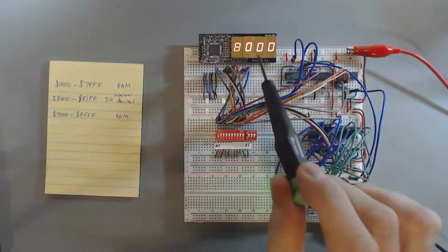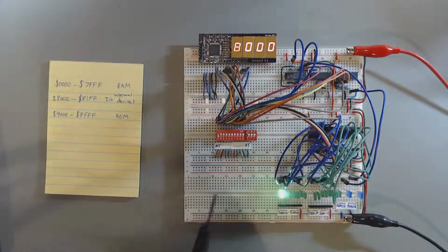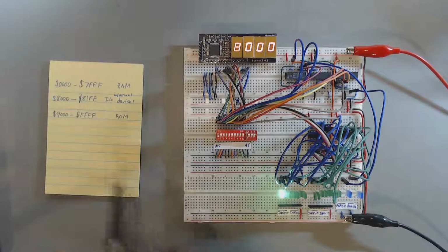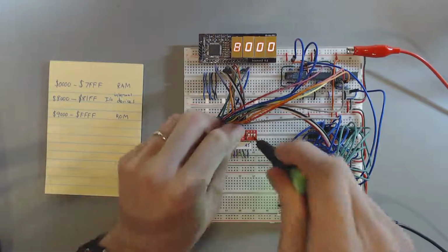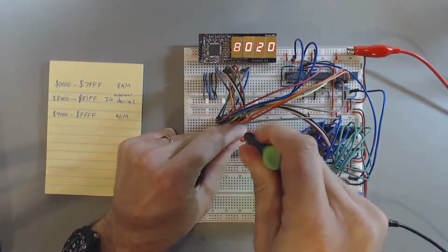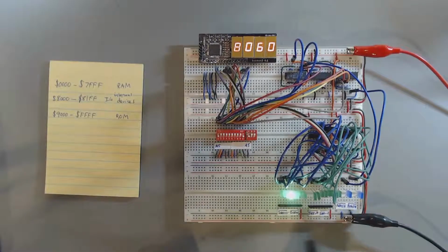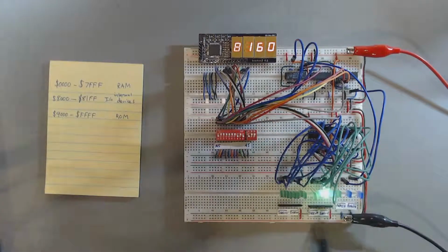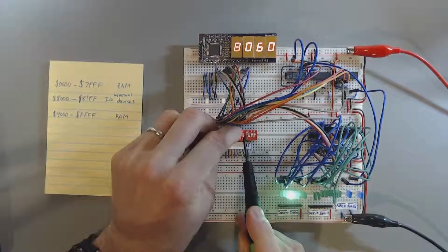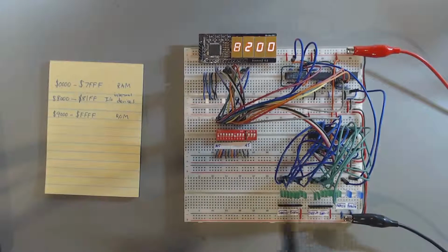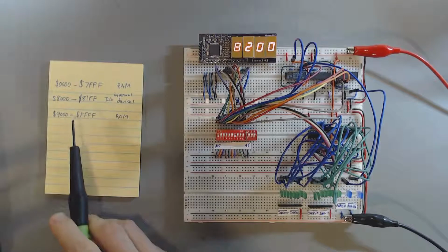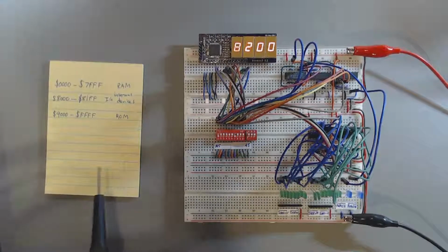All right, so addresses 8000 to 9000 are the 4K I/O region that we use for I/O devices. And the first 512 bytes of that region, from 8000 to 81FF, is what is decoded by these 2 supplemental 138 decoders into the 16 individual system chip enables. So what we find is that as long as we are generating an address below 8200, we are selecting one of these 16 chip enables. And depending on which pattern of dip switches we select here, we could select any of these 16. What we find then is that the moment the address gets to be 8200 or higher within that I/O region, we are no longer generating one of these chip enables, and essentially that means that the region from 8200 to 9000 is available for future expansion.